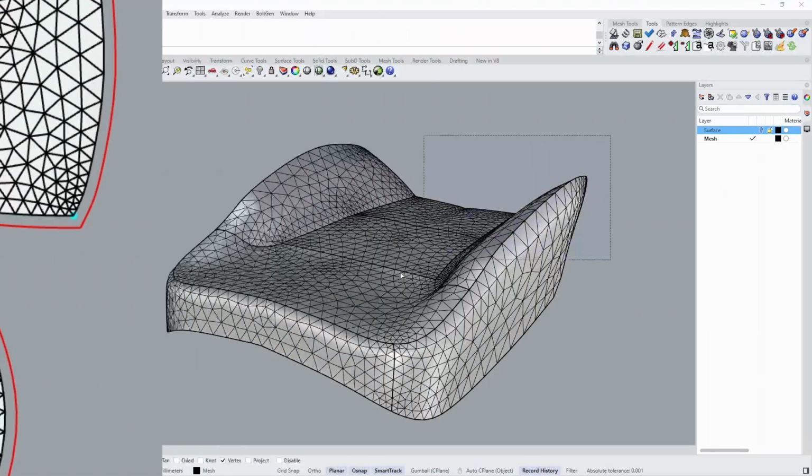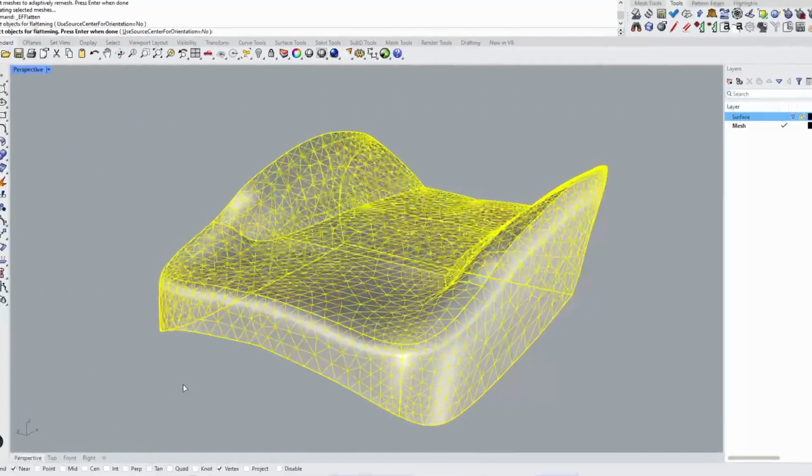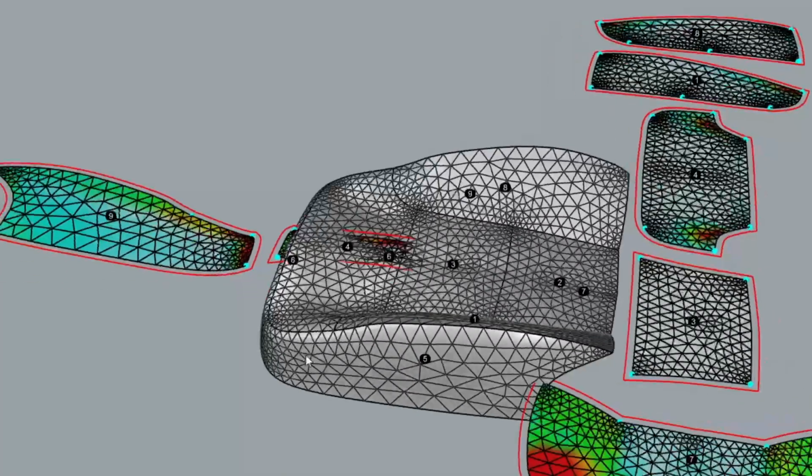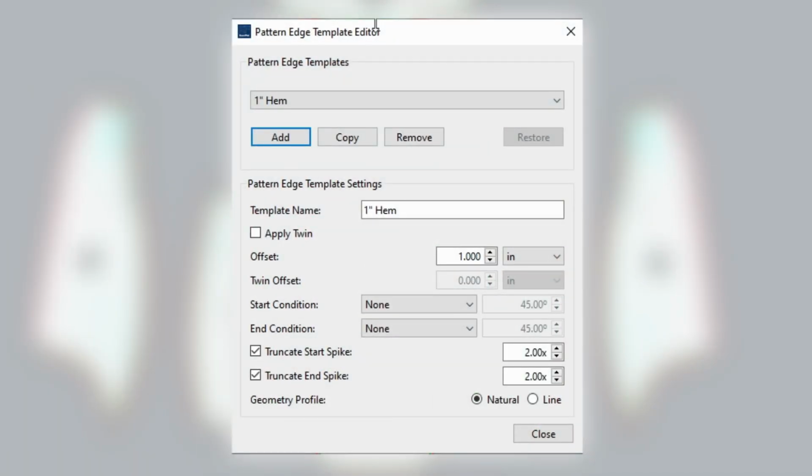For entire projects, use default settings. From the ExactFlat options, choose a template. Settings are applied to the entire project when converting from 3D to 2D. You can easily create new or edit existing templates.